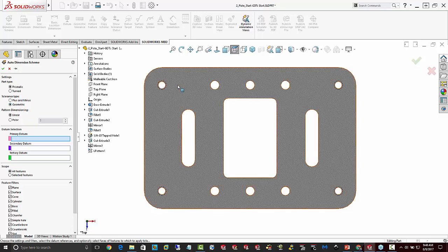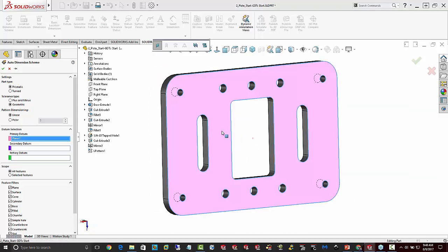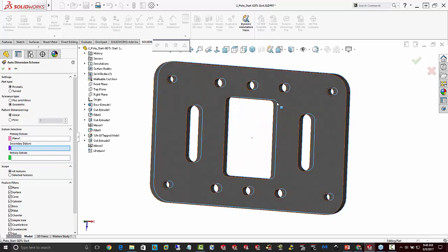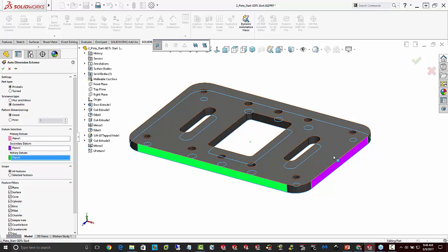And again, our hole pattern is still in a linear fashion. We want to define these datums. The plate will be placed on this face. Now I'm going to pick up the theoretical midplane of this part for the secondary and tertiary datums. I'm going to select this plane here, and that could just be a datum for our secondary, and then I could move down and use this plane as our tertiary. But again, I just want to pick up the center of the plate.